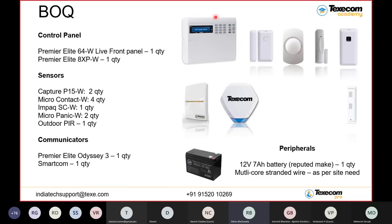So I have taken one panel. Along with that, I have taken an 8XP-W expander. Why? For the first floor area, because I am putting the control panel on the ground floor, which covers all the wireless sensors of the ground floor. Then I have to cover the first floor area also. So for the first floor area, I have taken one expander, 8XP-W. The 8 means this expander can take a maximum of 8 wireless zones.